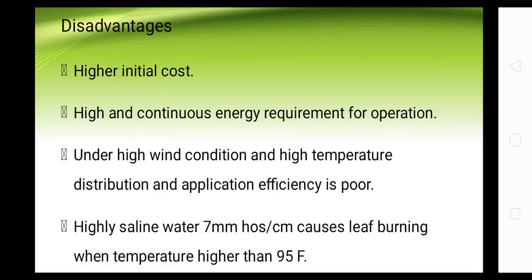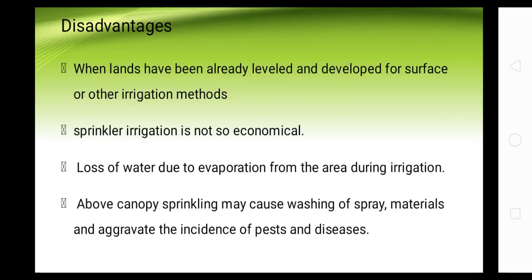Disadvantages: higher initial cost, and a high and continuous energy requirement for operation. Under high wind conditions and high temperature, distribution and application efficiency is poor. Highly saline water causes leaf burning when the temperature is higher than 95 Fahrenheit.